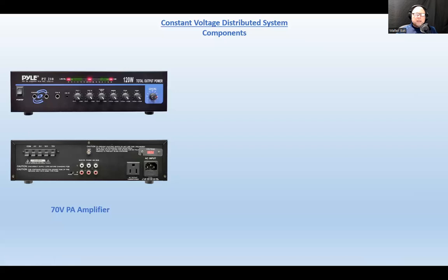Here's the thing. If you plug a telephone system into the designated input on that dry contact type of system inside the amplifier, and you have the volume selected to a certain level, and the main volume adjusted to a certain level, then the electronic circuitry does have some noise. So you will hear some kind of hiss or maybe some slight buzzes, and that would be transmitted from the speakers all the time.